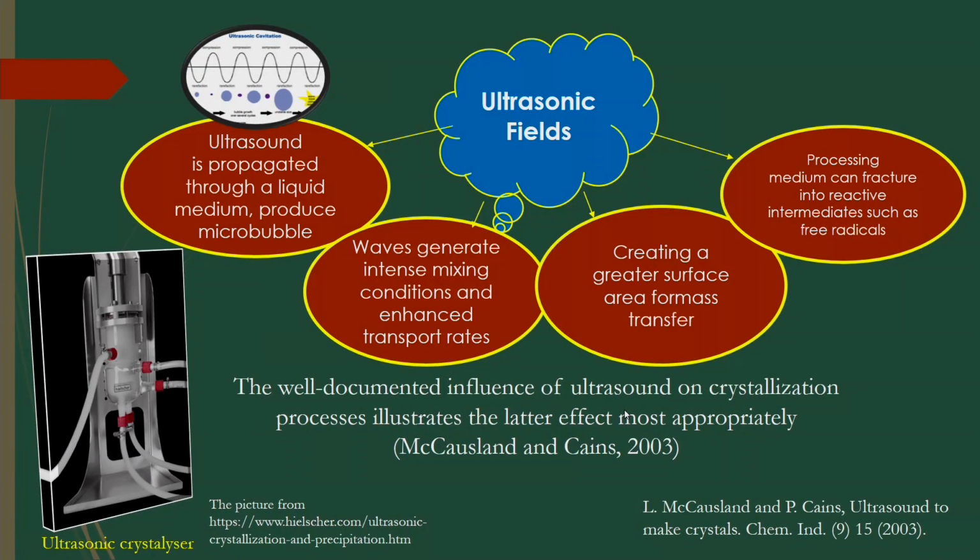In this case, whatever ultrasonic waves are generating, you will see fluid mixing will be higher based on these ultrasonic waves, and in that case the transport rates can be increased based on this ultrasound operation. Also, it creates a greater surface area for mass transfer, because microbubble production, and even nowadays nanobubbles, are produced for medical operations to get more surface area for gene therapy and even drug delivery operations in cancer cells.